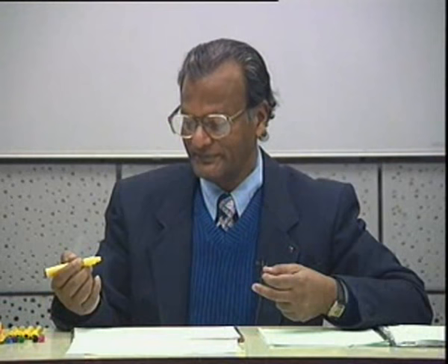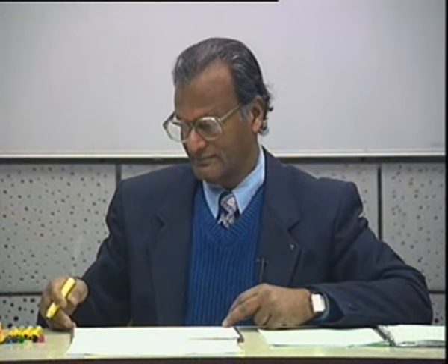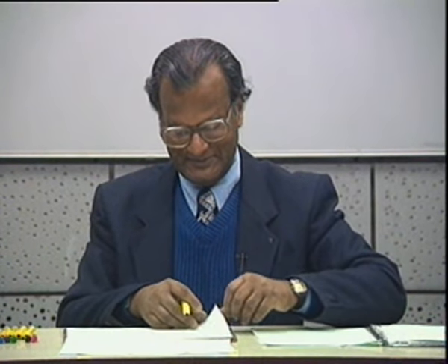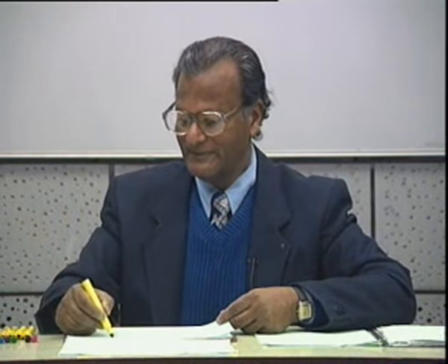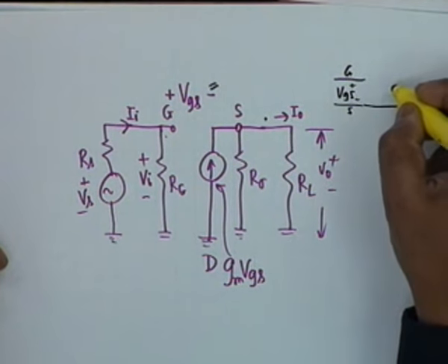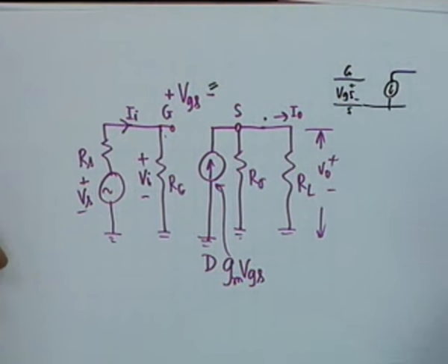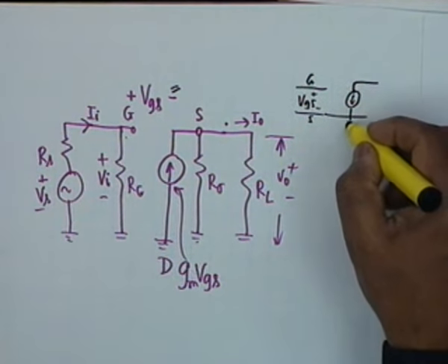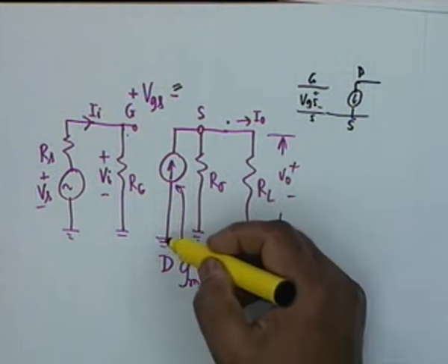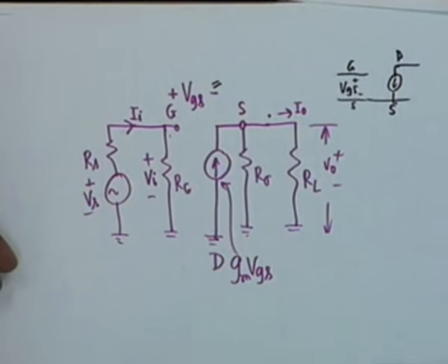So in that case, in case of common collector amplifier, the direction of IC is opposite to the conventional amplifier. No, it was the same. The gm V pi had come from ground to the emitter. It's the same. You have to remember that our equivalent circuit is VGS, and then you have the gm VGS here. Now S, D is grounded, so from D to S, that's why this is taken care of.